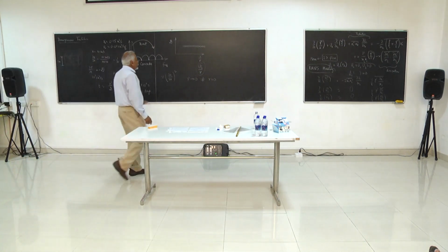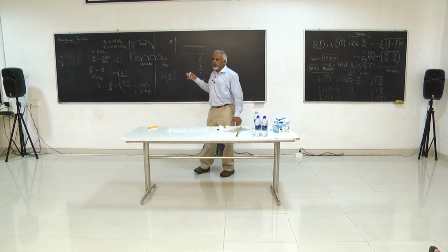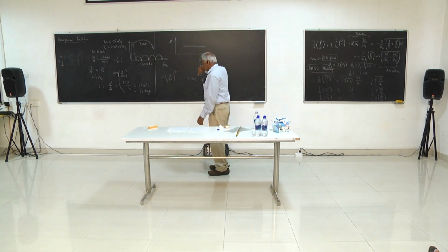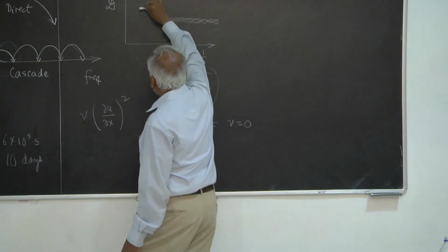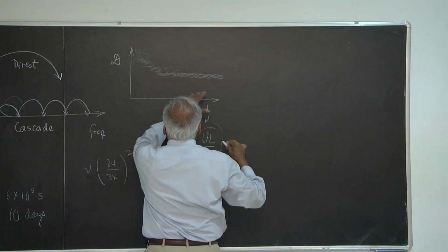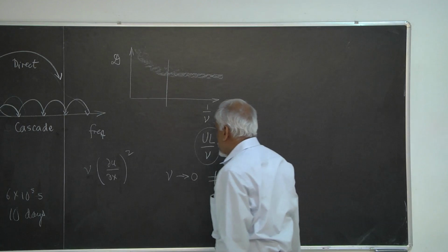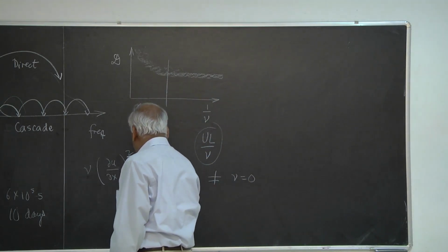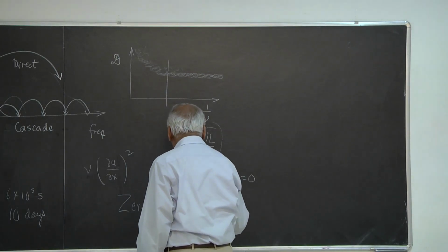Now, nobody knows how to prove it theoretically, but empirically this is known. I can give you references to some papers, but in all of them, the behavior is a little bit like that, coming down, and for high enough Reynolds numbers, it is independent of viscosity, and people who are very clever want to call it the zeroth law of turbulence.